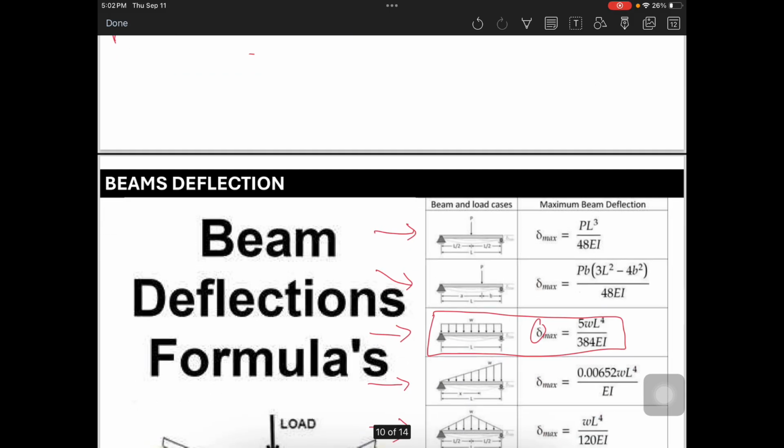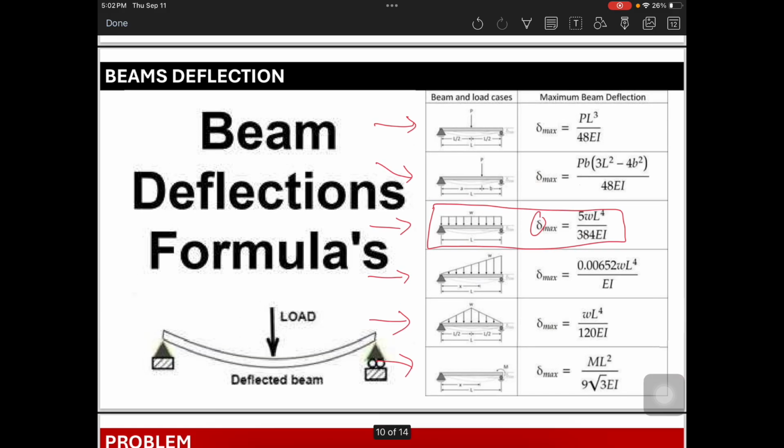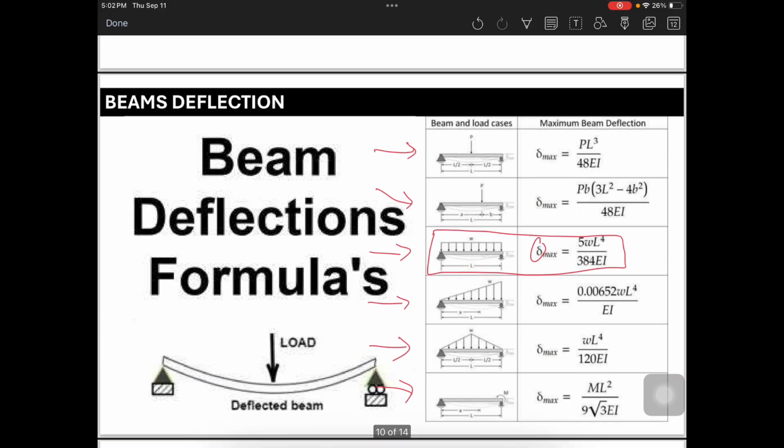Okay? So, that's all. Next meeting will be quiz natin. Ang scope is design ng beam, module 4 and 5 yon. Dahil ang design ng beam requires 3 checks: first is flexural strength, second yung shear strength, and the third itong deflection check. So, that comprises yung serviceability check niya, itong deflection check, and yung strength check niya is flexure and shear strength. Okay, thank you, bye.